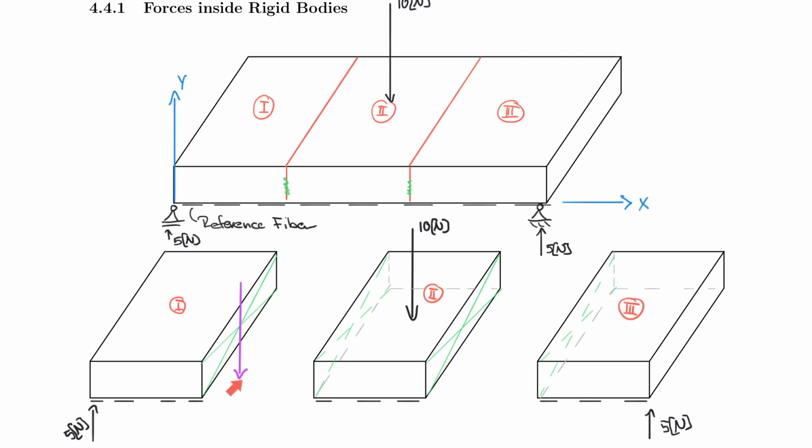But now we have this imbalance, or we can potentially use this force to bring the system in the vertical direction in balance. But the trained engineering eye already sees that these forces, even if they have the same value, 5 Newton and 5 Newton, would cause this system or this rigid body or the part of the body to rotate. In this case, it would rotate clockwise. So we need to do something against that.